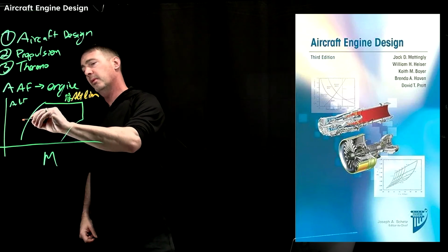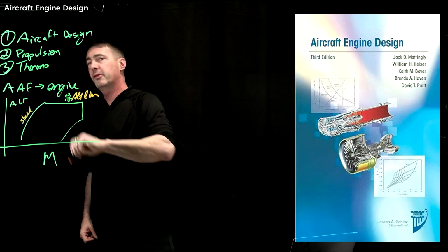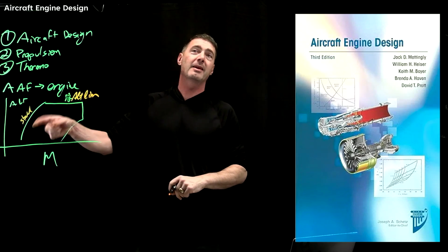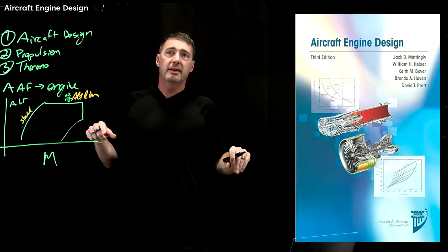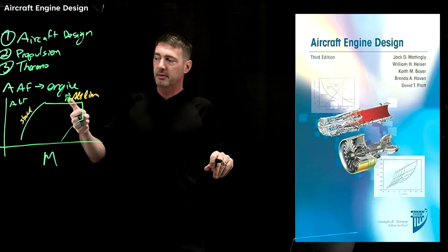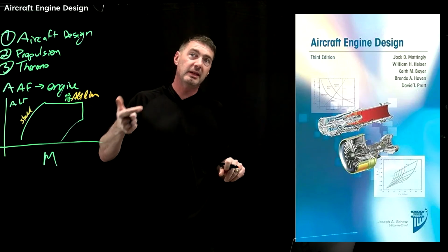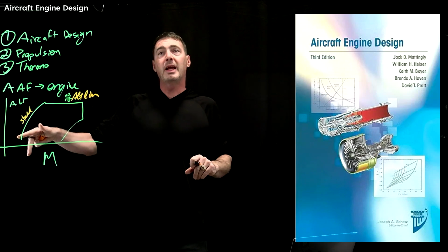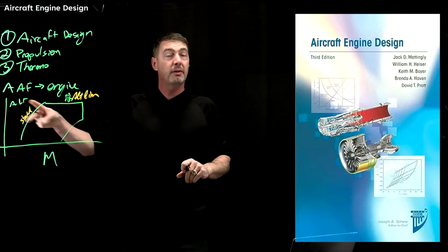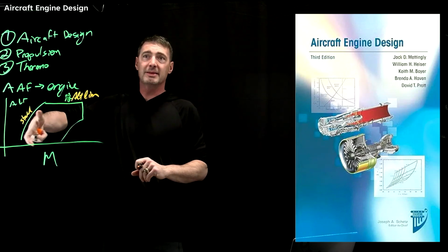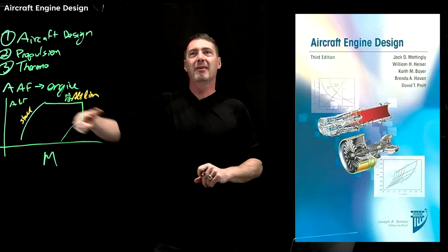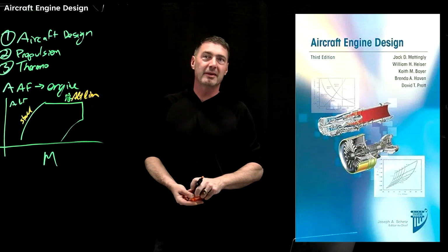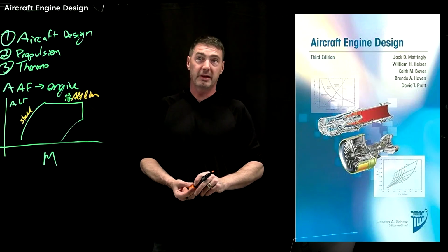Okay, on the left, this is stall. Your aircraft can't have enough lift between the wing. Pressure is related to density and your speed squared, and so it's not enough to keep the aircraft in the sky, so you're going to stall. Now, it's going to happen at different speeds for different aircraft. This line is not set. Absolutely, if you're a glider, it's going to be very, very different than if you're a fighter jet.